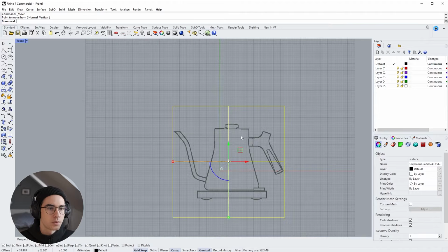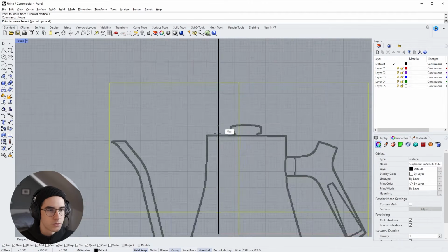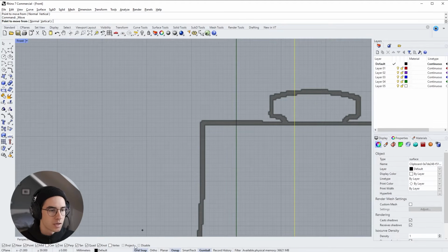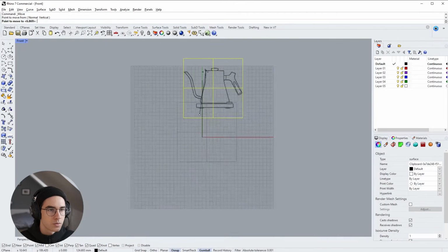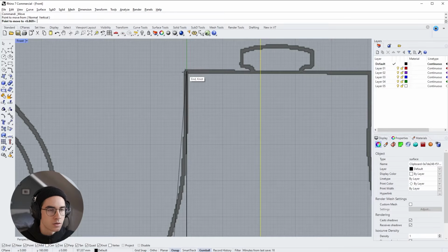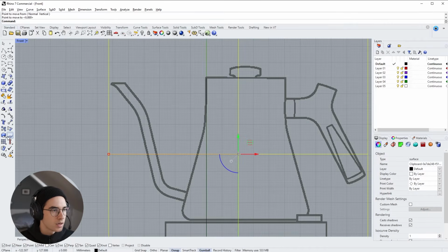All right, now we want to resize this image. So go to the left, go to the Move tool, and I'm seeing that I have Grid Snap on. I'm turning that off quickly, and just go to one of those corners and move that up to the end of the line. And next we want to scale the image, and we want to scale it in 2 dimensions. So go right click or long click on this scaling tool and choose Scale 2D.